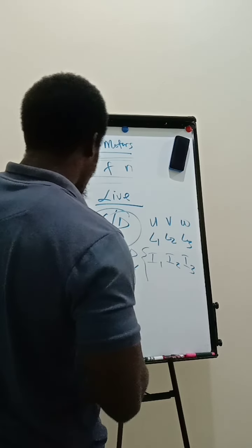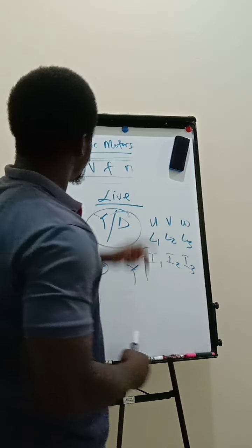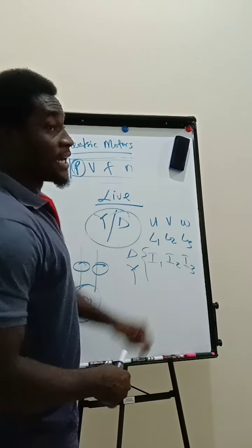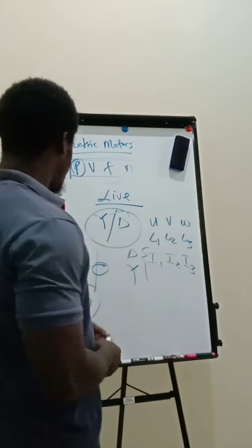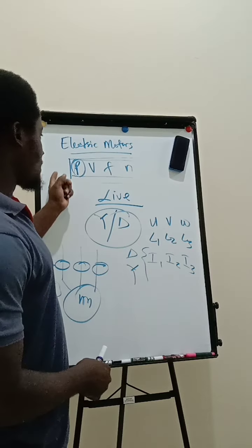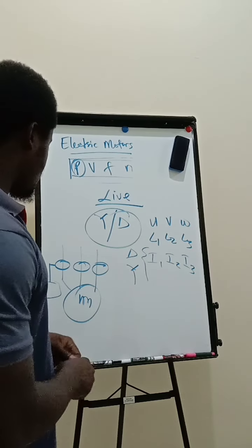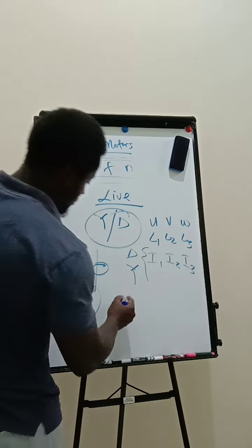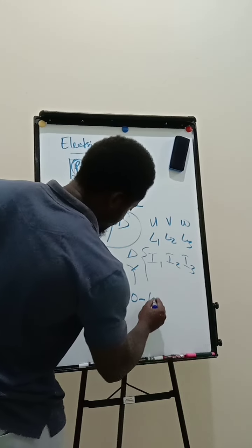After taking that, we compare with the nameplate, which is written by the manufacturer, to ensure that the current we measure is greater than or equal to that of the manufacturer, since we are carrying out the test on no load.